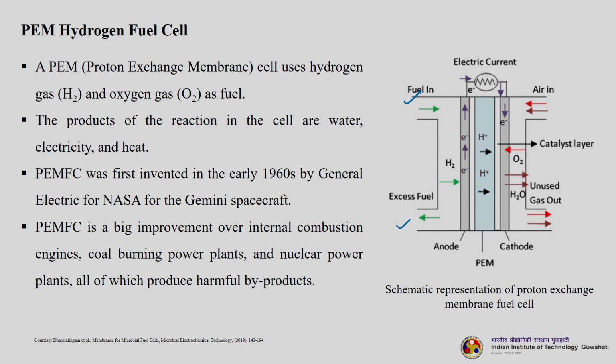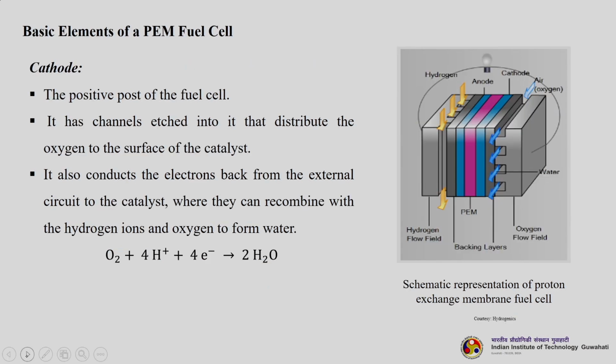So, it comes in contact with the anode and it generates the electrons, then it passes through this, your PEM, proton exchange membrane, right. It is exchanging only the protons, it is a semi-permeable membrane, it exchanges only protons, nothing else, right. So, the proton passes or diffuses through the membrane and then reaches the cathode side, where it gets converted to water, okay. And by virtue of the electron transfer, electricity is getting generated here, right, and you can harvest it then. So, let us quickly go through the different components of this one.